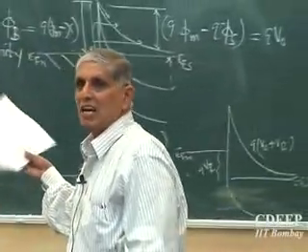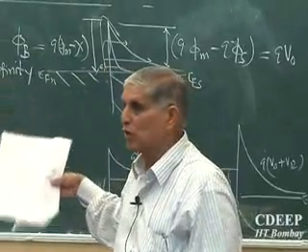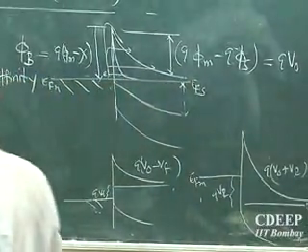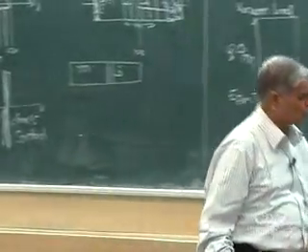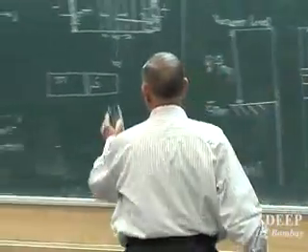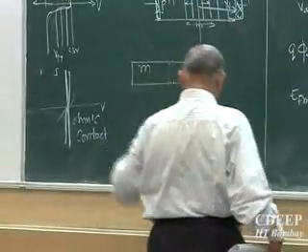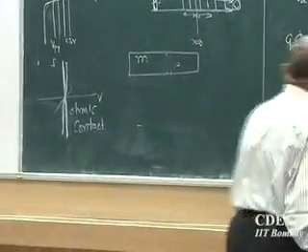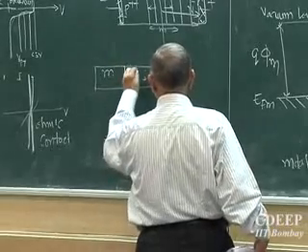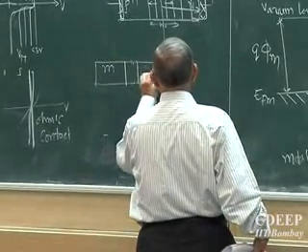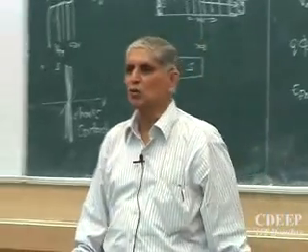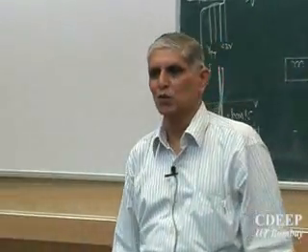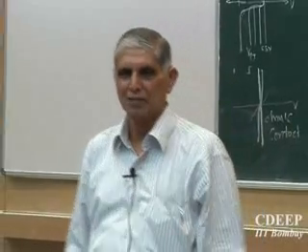So is that clear why I actually use this? I am going to go to a MOS capacitor now, and please look at what I am now going to do. A Schottky barrier has metal and semiconductor. I am going to introduce between semiconductor and metal an insulating layer.